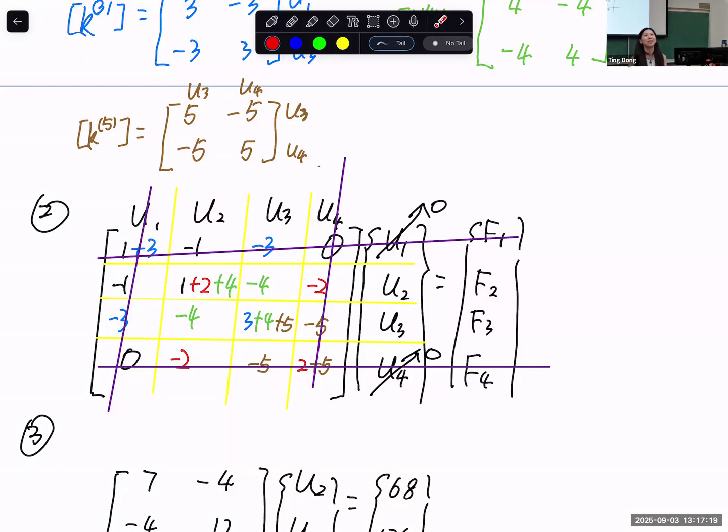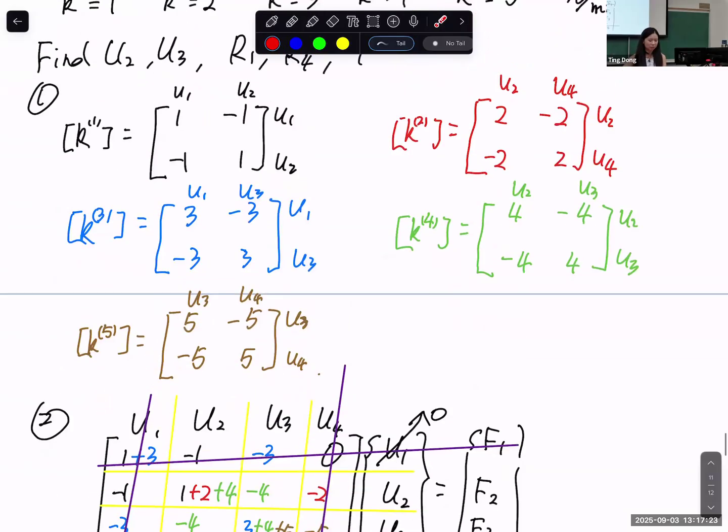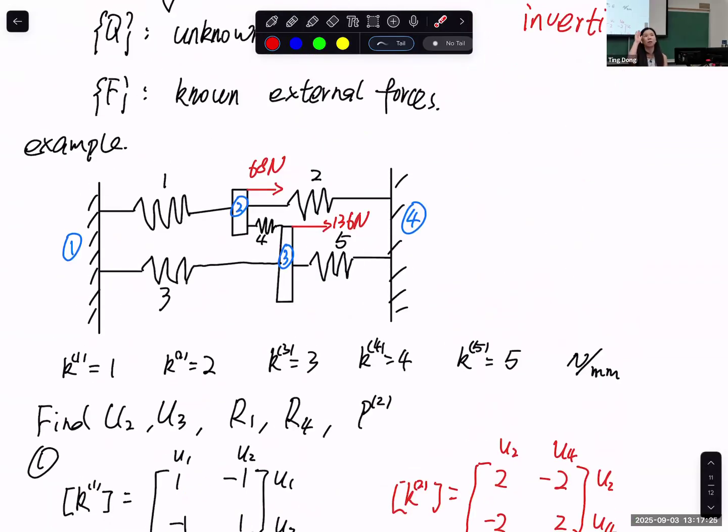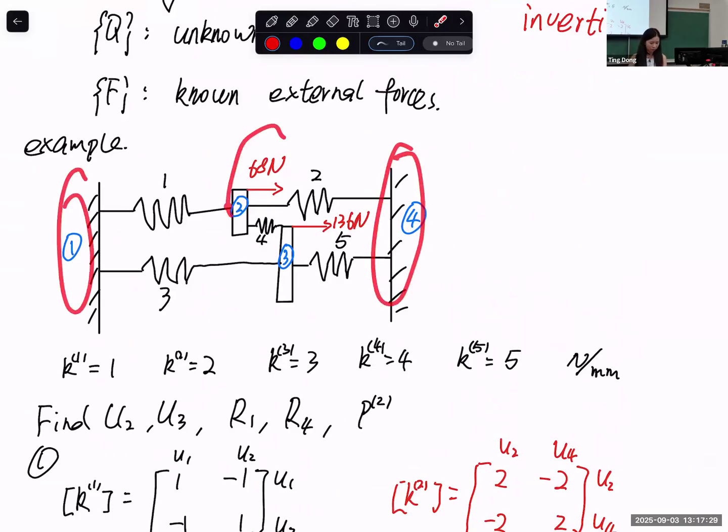They are not 0. Yeah. If we just imagine, let's forget about FEA. If simply from statics, F1 and F4 equal to 0, and you have F2 and F3 applied, you just fly away. Make sense or not? For our FEA or mechanics of materials statics problem, our system should be in equilibrium.